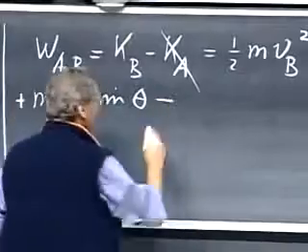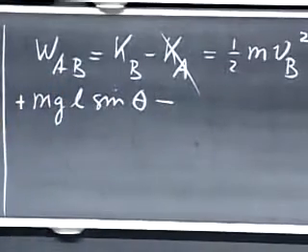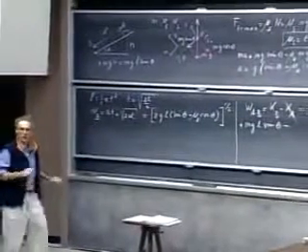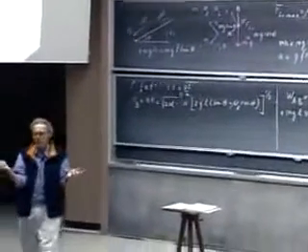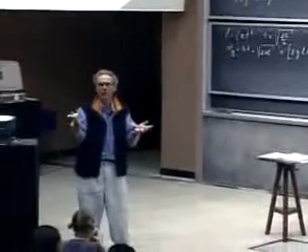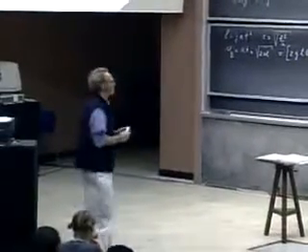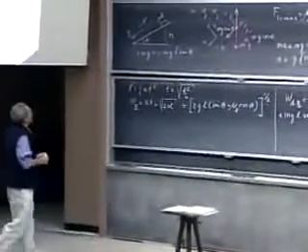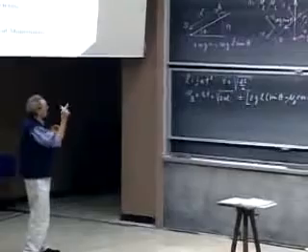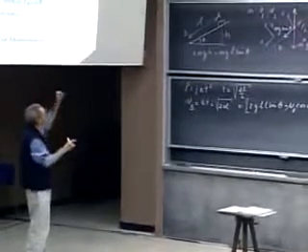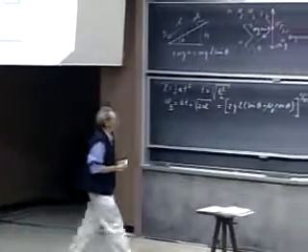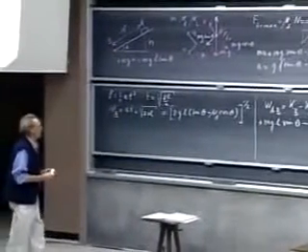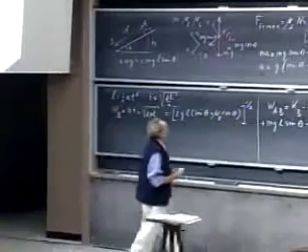And now we get a negative contribution by friction, because the frictional force is uphill, but the motion is downhill. They're 180 degrees opposite, so I don't have to worry about the dot product, because the cosine of the angle is -1. And so I can ignore the dot and simply take that force, the frictional force, and multiply it by that distance L, but I have to, of course, take the minus sign, because the cosine of that angle equals -1.